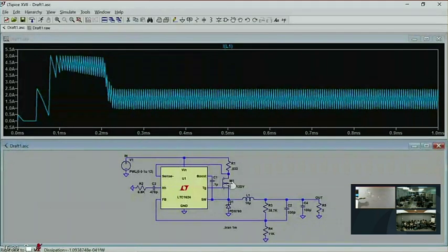Okay, now the reason for doing that is because this is just a better way of doing it. Okay, you can think of this as an op amp without the output buffer. Okay, the output buffer, what it does is it buffers the voltage. You can drive some unknown low impedance, but I don't have to drive some unknown low impedance, so I don't need the voltage buffer.